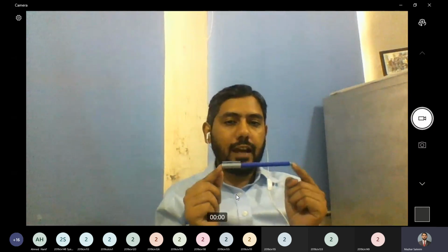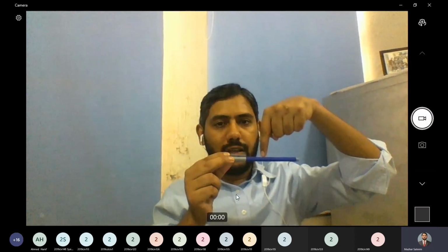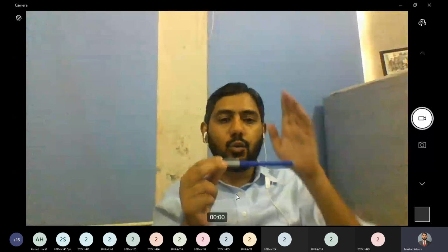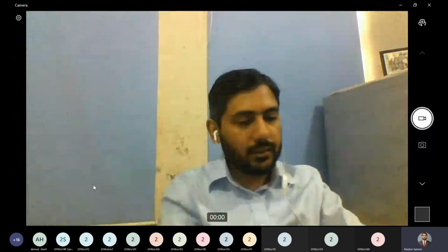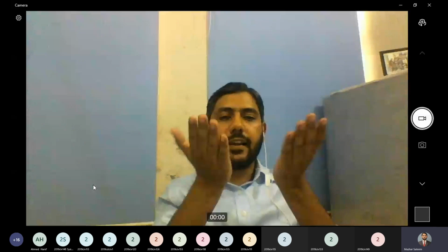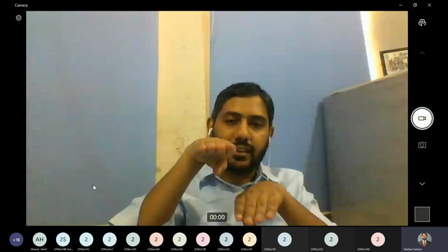Okay, that's fine. So we have a beam, and when I apply a transverse load on this beam, this load has two tendencies. One tendency is to break the member. If I consider one section here, the tendency of the load is to slide one section relative to the other.